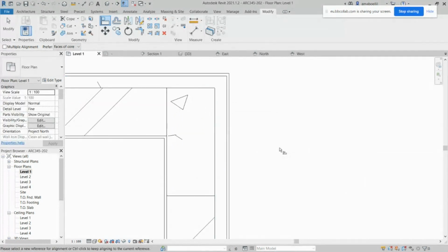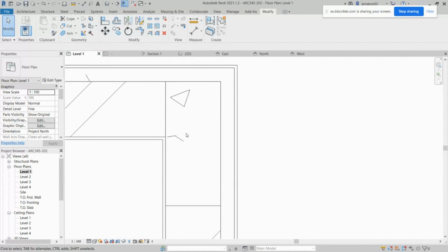It's going to be aligned perfectly like that. So here I have a right construction detail. The column is embedded in the walls, and the finishes come afterwards, like plastering and coating, all over the structural material. It's going to be aligned perfectly. This is really what I need to see in your drawing, and this is going to be critical while criticizing the quality of your drawing.